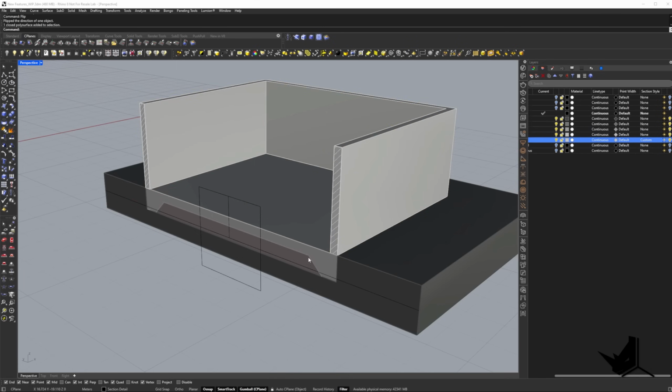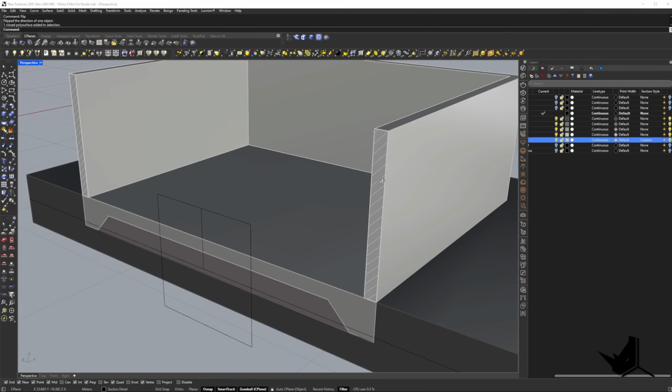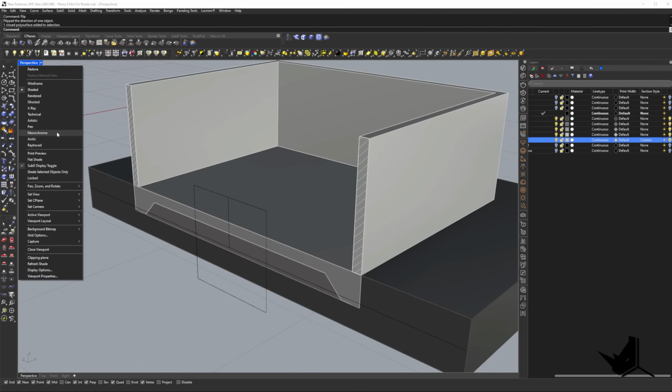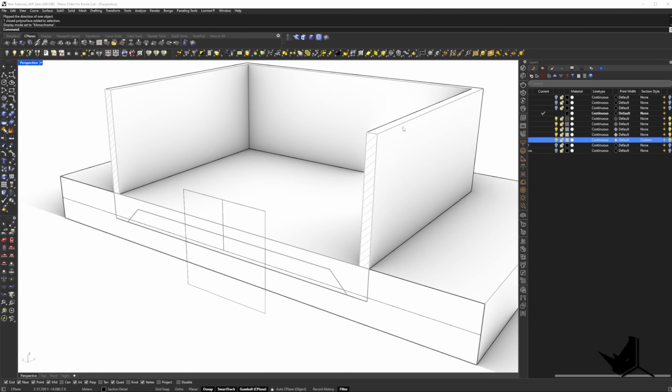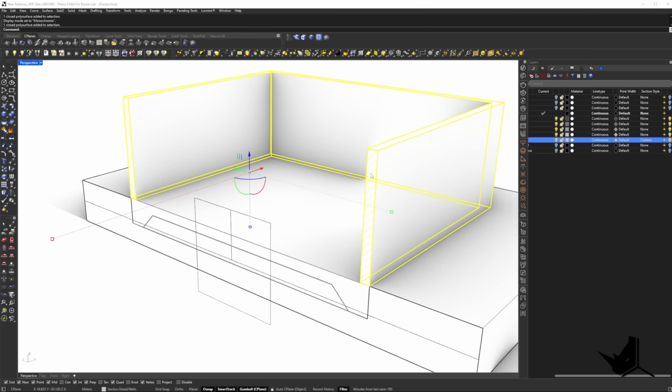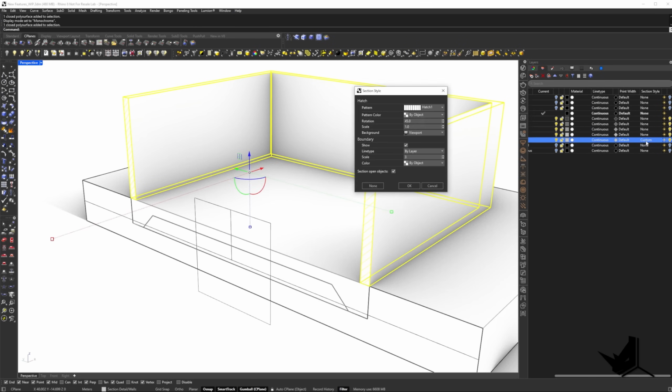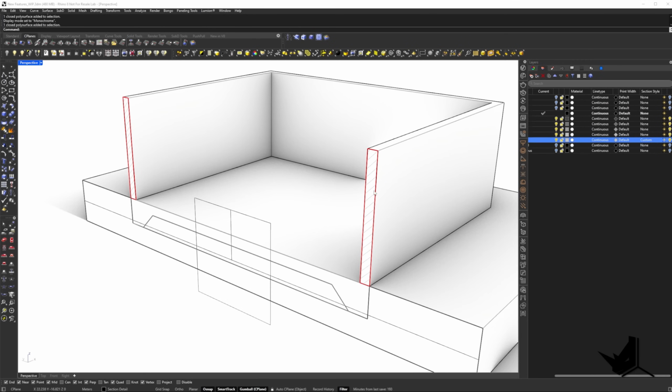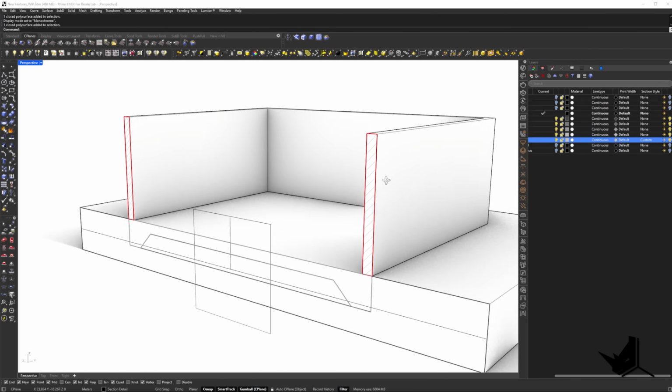You will see right away that we have that hatch style applied. Even if you go to, let's say, Monochrome, you will see that hatch applied right there. Of course, you can modify that anytime by clicking on the custom and modifying the color. For example, the color is set to object here, but we can put some other color, let's say, red. Click OK, and you will see that we're going to have a different type of output here.